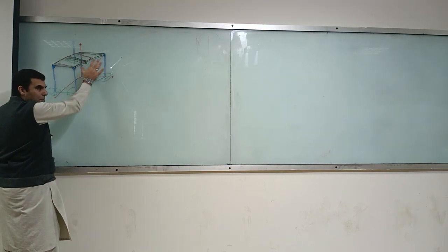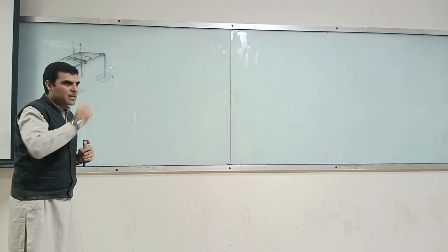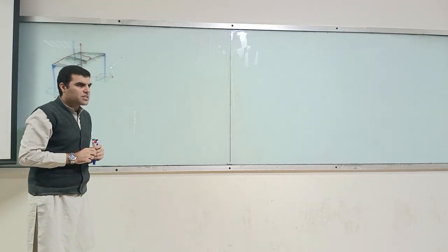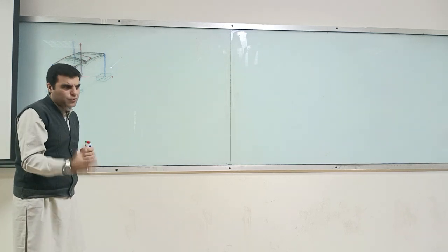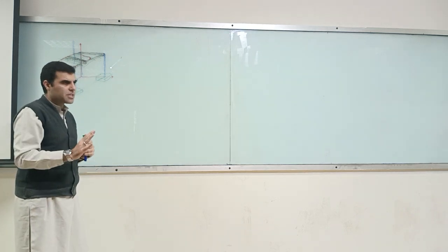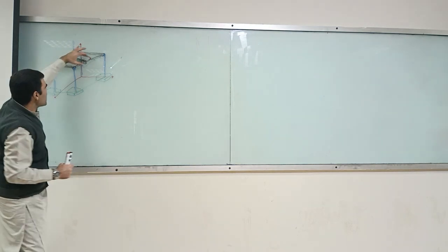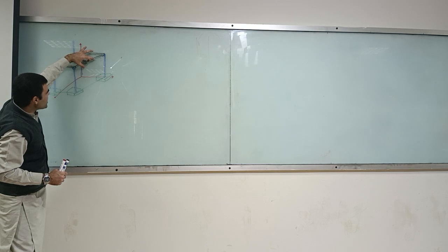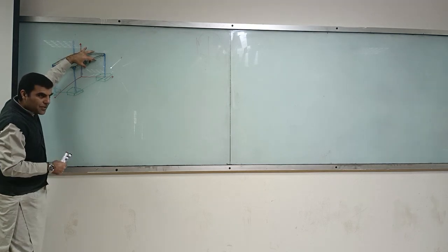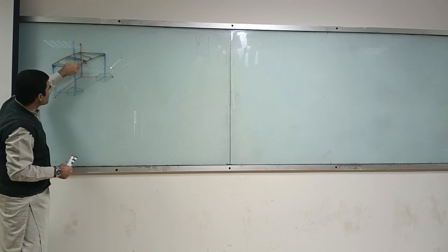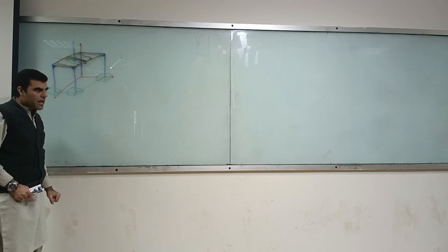So if I multiply that load, which for example say is 3 or 4 kilonewton per meter square. Imagine that's 4. It's not 4 normally, it's 1 to 2 kilonewton per meter square, but imagine it is 4 kilonewton per meter square. So I will multiply that with this length. So what would I get? Per unit length. And that per unit length will be the load which will be applied on this beam. Do you understand my point?